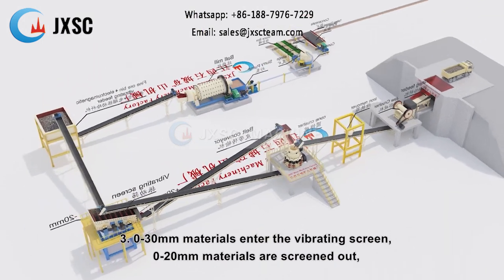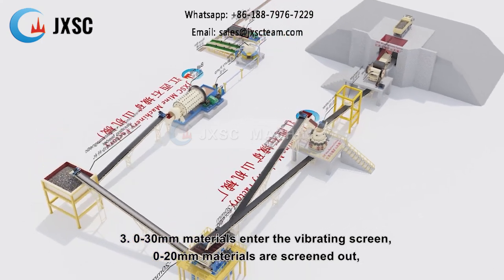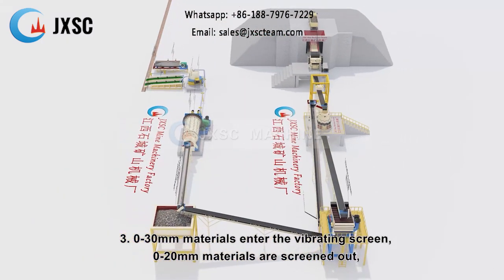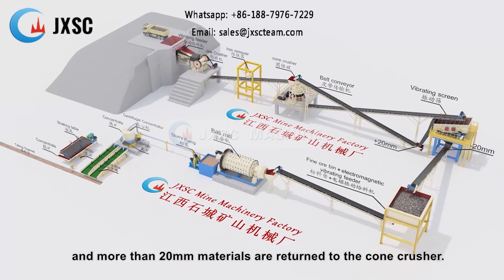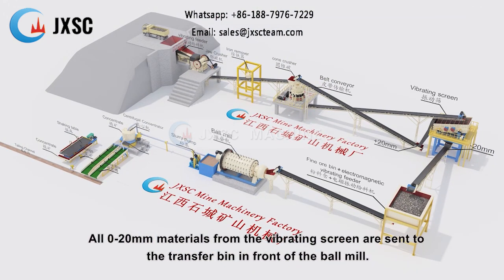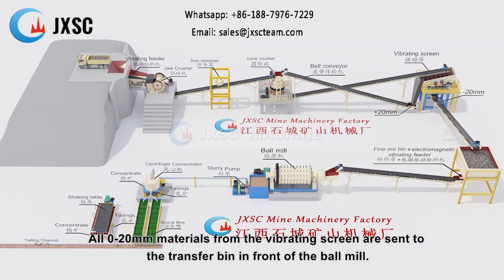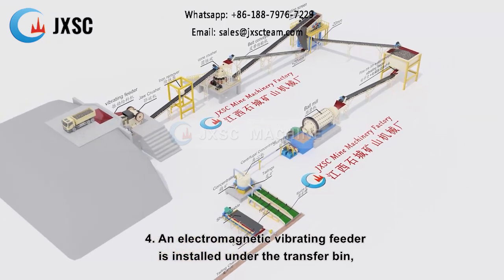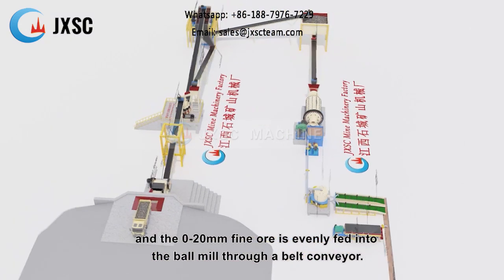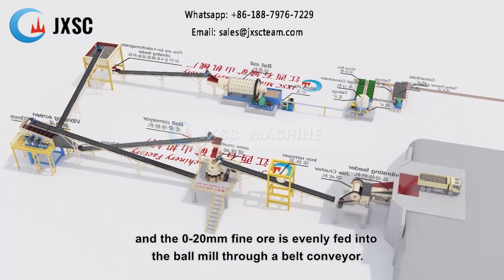3. 0 to 30 millimeter materials enter the vibrating screen, 0 to 20 millimeter materials are screened out, and more than 20 millimeter materials are returned to the cone crusher. All 0 to 20 millimeter materials from the vibrating screen are sent to the transfer bin in front of the ball mill. 4. An electromagnetic vibrating feeder is installed under the transfer bin, and the 0 to 20 millimeter fine ore is evenly fed into the ball mill through a belt conveyor.